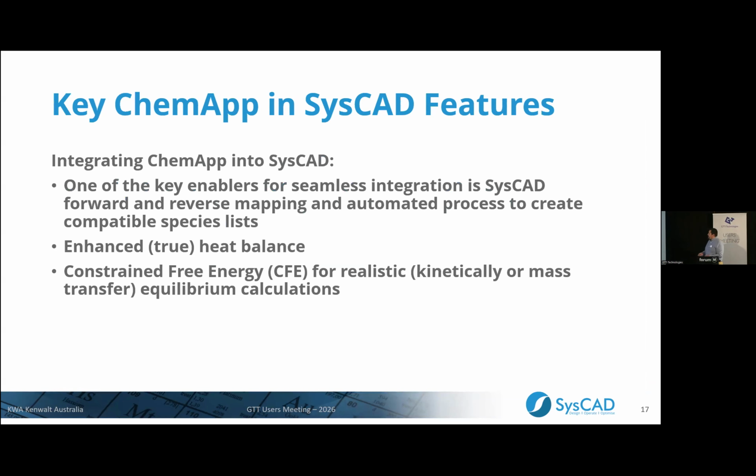So just to finalize, some of the key features of integrating ChemApp into SysCAD: it allows us to bring in true heat balance. That's something that SysCAD is not capable of doing on its own because it doesn't have solution thermodynamics in its database. But when we bring ChemApp into SysCAD, we can say, okay, I want the heat balance to be done with full excess parameters and so on.